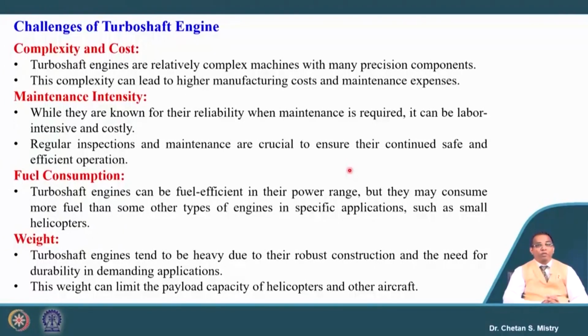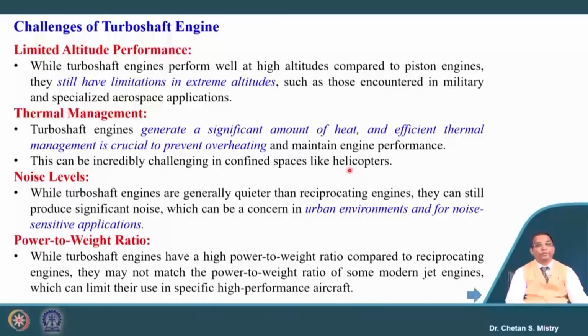When we talk about fuel consumption, it is less compared to the reciprocating engine we are discussing, but when we compare with other gas turbine engines, it is a little poor when we are talking about small helicopter engines. The weight is comparable with the reciprocating engine, but when we are talking about aero applications, then the weight is higher, and that is the reason it puts restrictions on the application for aircraft and helicopters.